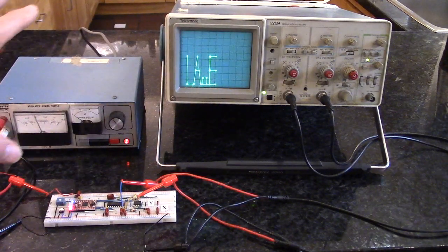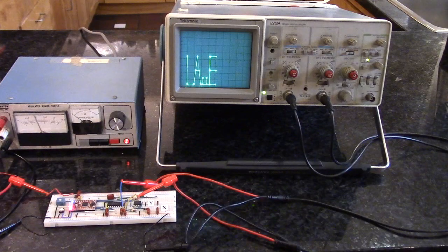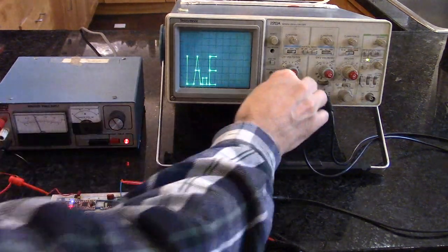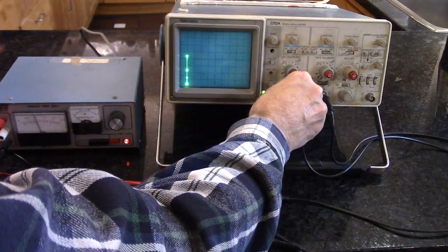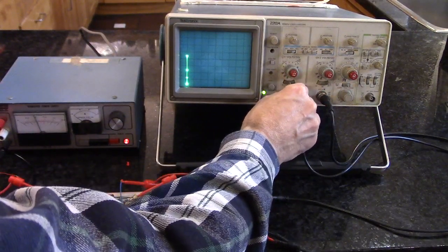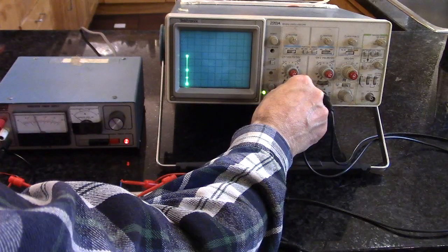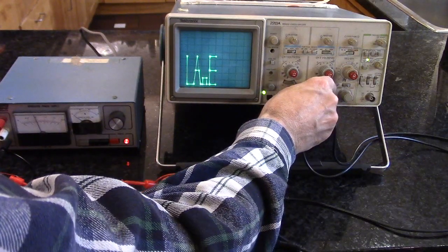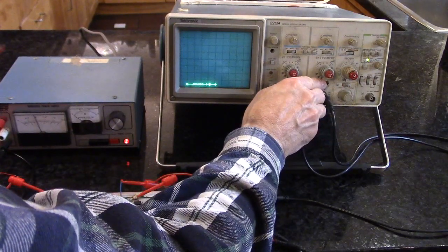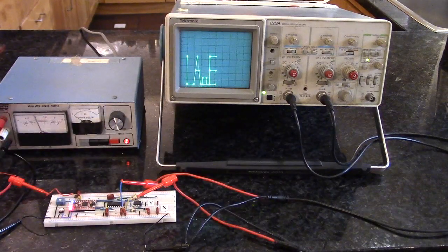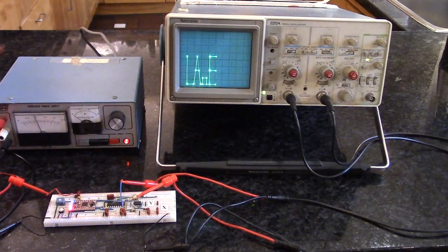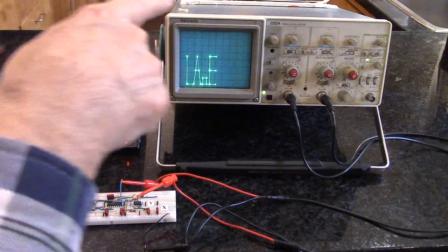This is an analog scope in XY mode. That means that channel A sets the X direction, and right now it's about half a volt per division, and channel B is the Y direction. So I turn off channel 1, and we don't have anything in the X direction. I turn off channel 2, we don't have anything in the Y direction. And what we're doing is we're outputting voltages, and the voltages we're outputting are the dots.